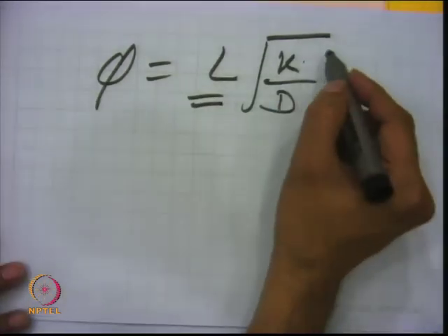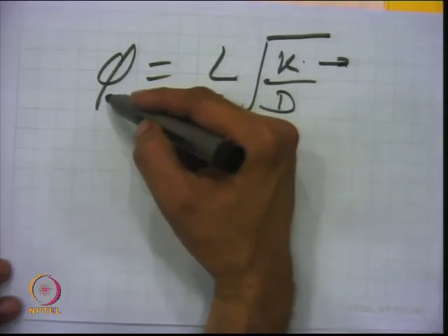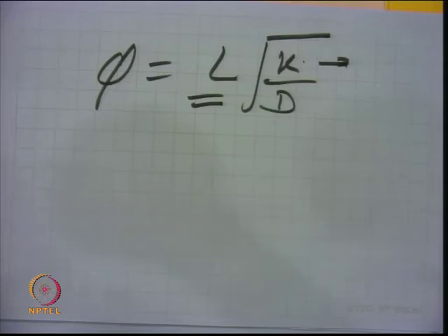Second thing is the k dependency, because you need your phi small. When your k is very high, that is, the temperature is very high, k is a function of temperature. When the rate constant is very high, then chances are that diffusion may be dominating. So, that is diffusion control. So, temperature should be controlled when you look at the kinetic study.